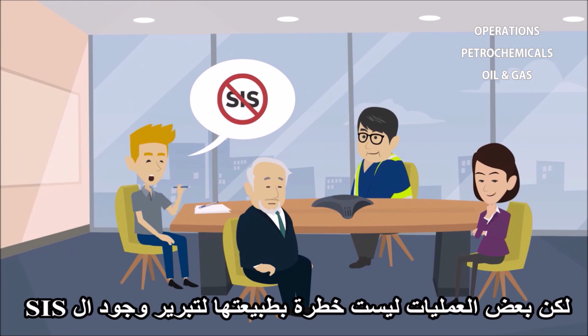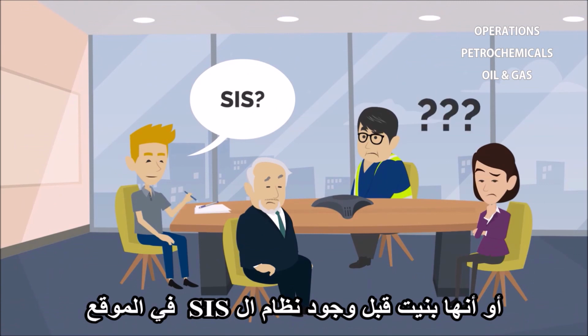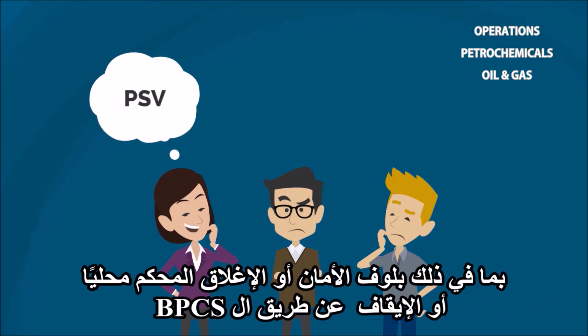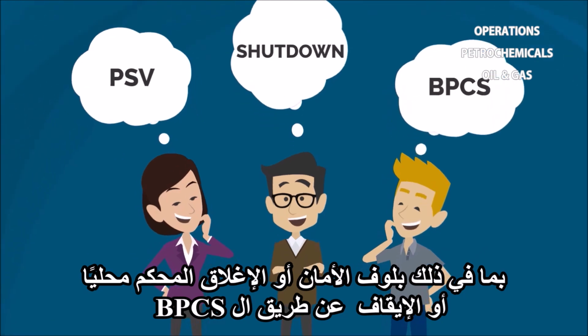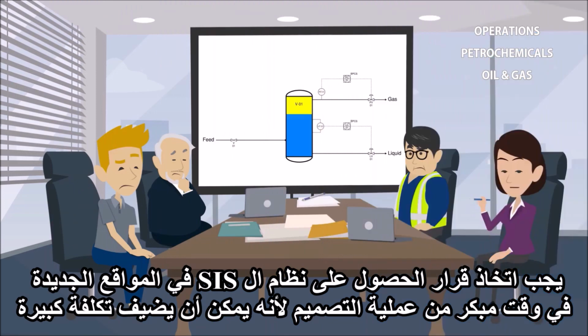However, some processes are not inherently hazardous enough to justify having an SIS, or they were built before having an SIS at a facility was common. Some processes can mitigate hazards by using other means, including pressure safety valves, locally controlled shutdowns, or shutdowns wired through the BPCS. The decision to have an SIS at a new facility should be made early in the design process, as it can add significant cost.